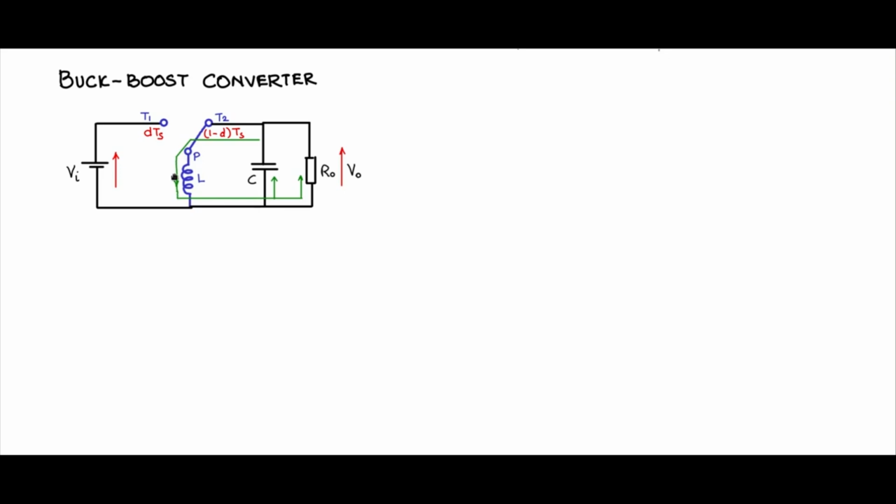So the inductor current continues to flow, but when it is flowing through the capacitor, look at the direction. The charge on the capacitor will be plus minus in this fashion, which means you will have a negative voltage. V0 will be negative and I0 will be flowing in this path, in this direction. So that is one difference that you would find in the buck boost converter with respect to the buck and the boost topology.